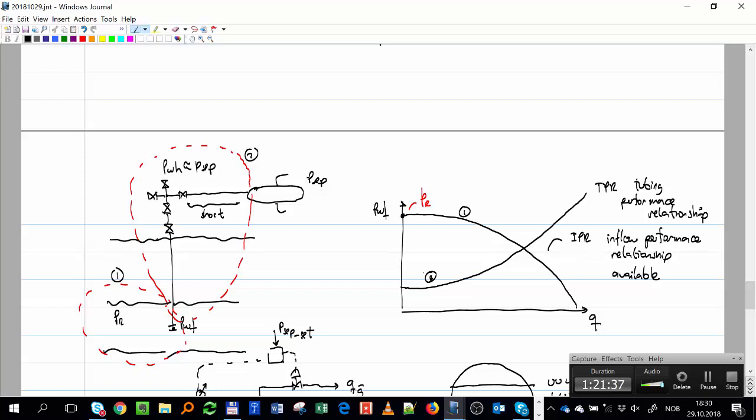The reason is that in every well, in every production system, we have two boundaries of fixed pressure. We have one boundary in the reservoir, which is not really fixed, but it changes so slowly with time that we can say at one point in time it's constant, today and next week. And the separator is always constant, that I never change. So I have two, and I can use that analogy. Going to any point that I choose, I can calculate, co-current, the available pressure, and counter-current, the required pressure.